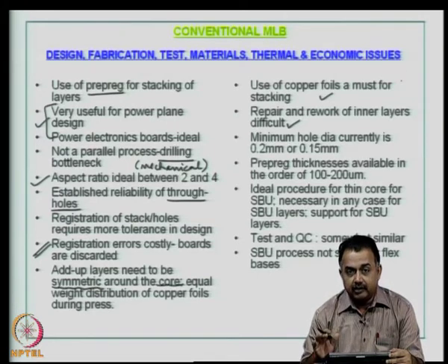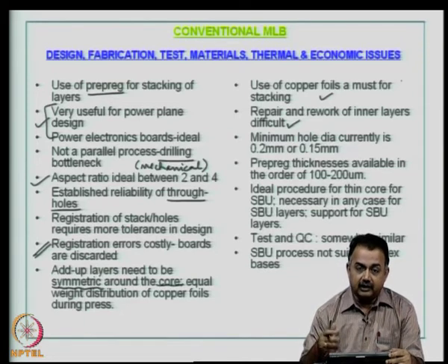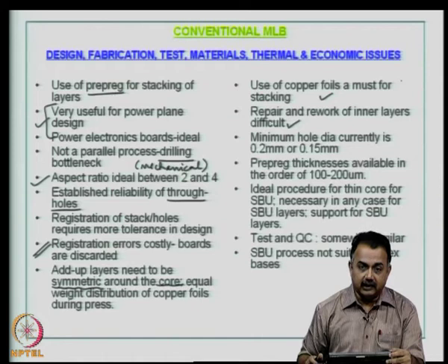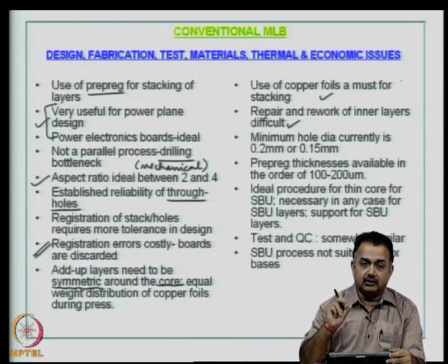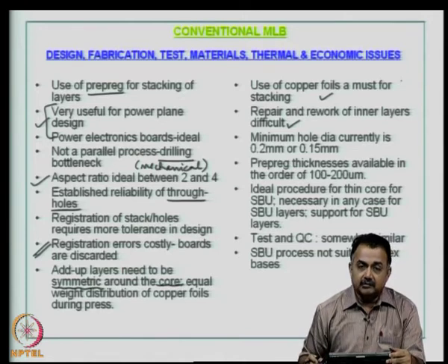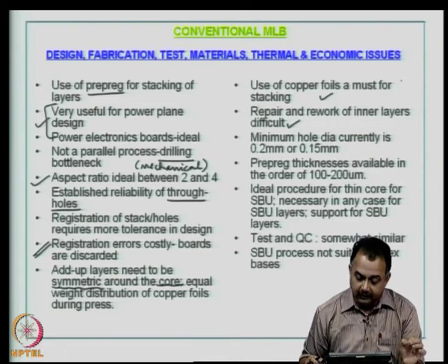Isolation of tracks is very important, and you have to make sure that these are maintained once the number of layers are stacked in a multilayer press. So, we want to maintain the originality of the inner layers in terms of electrical performance as well as dimensional stability.